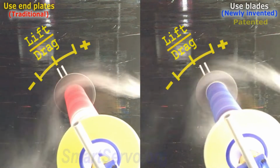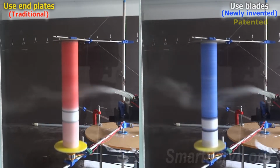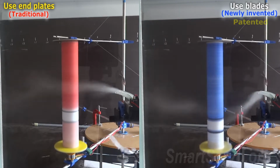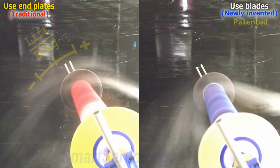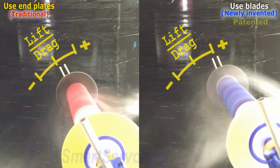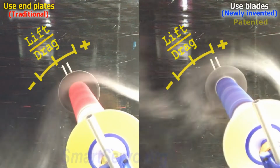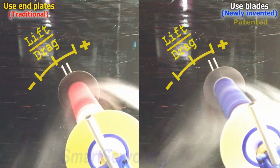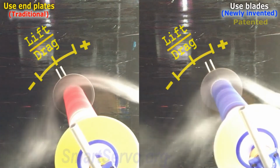Let's look at the smoke path at another height. Move the smoke blower to the center of the rotor, so that the smoke is away from the ends. Observe the smoke path again. View from the bottom. The situation is similar, although the smoke is further away from the blades. The boundary between the red rotor and the smoke is still obvious. The smoke is still closer to the surface of the blue rotor. Indicates that the blade still has an effect on the airflow in the center of the rotor.